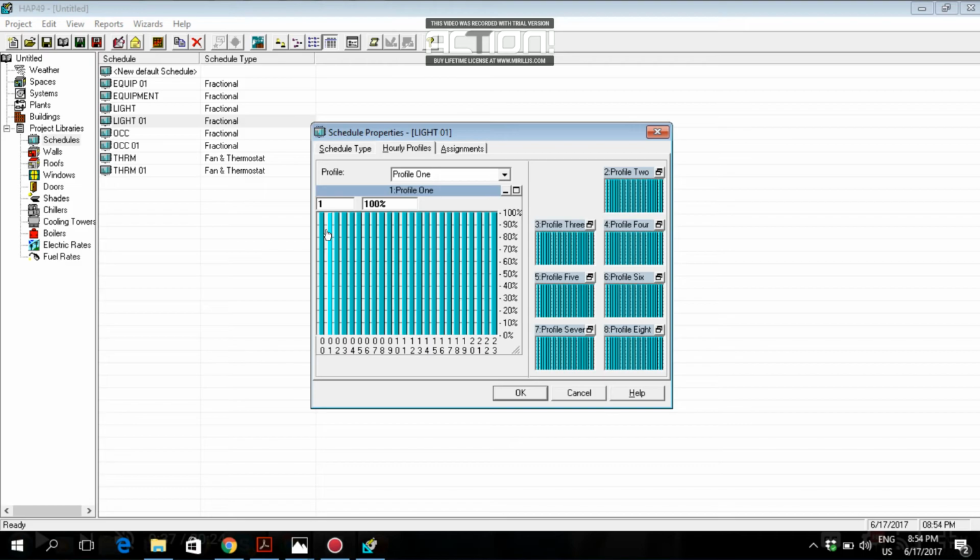This is the basic engineering principle: the capacity of any machine should be more than what is required. Later on we can add some accessories to that machine so it can drop down the operating hours depending upon the requirement. But when you are going to calculate the load, you need to calculate for the peak load. That's why in the normal procedure we just calculate for 24 hours.